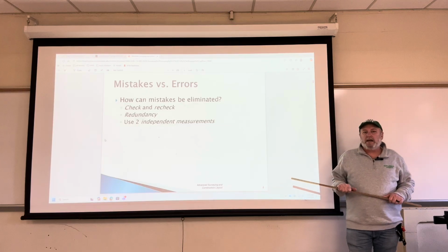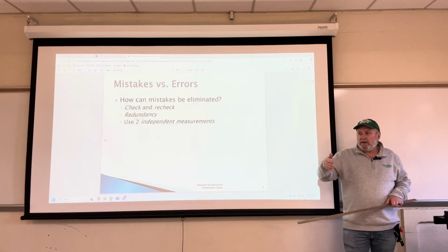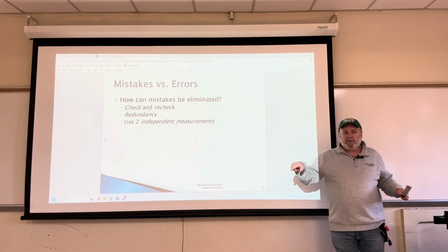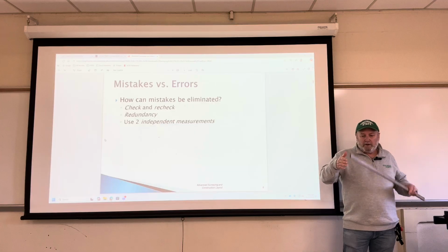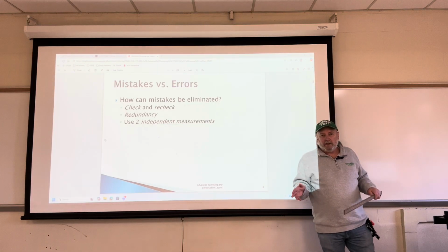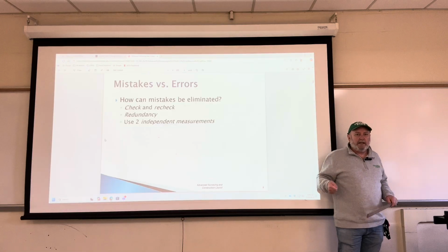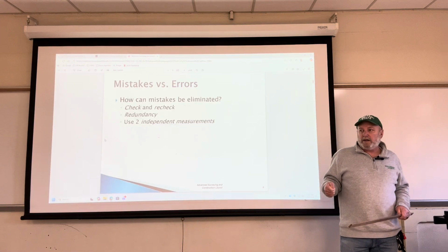When we get out in the labs, we'll lay out a building, for example. We'll set the corner of the building. We'll put some offsets at each corner. Take a tape measure. We know what our offset distances are. We can calculate what the diagonal distance between the offsets should be. We can take a tape measure, pull between our offsets just to verify that they're square and they're correct.